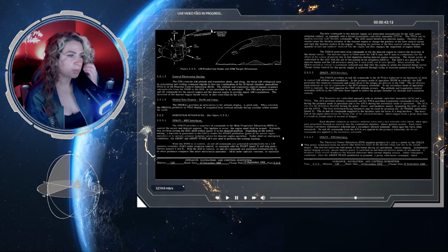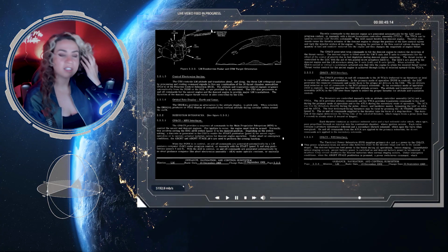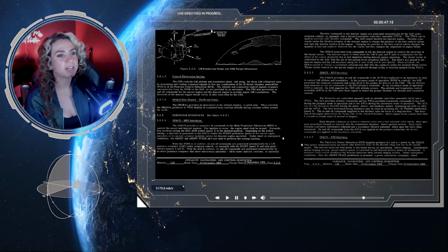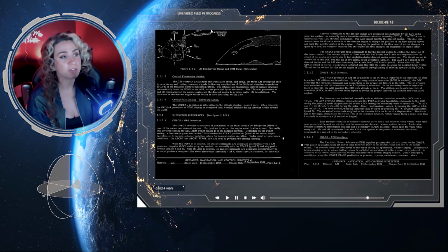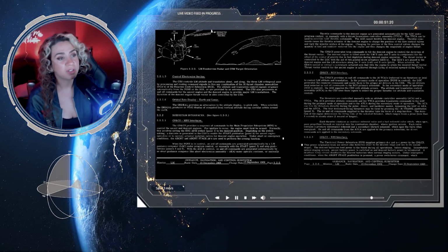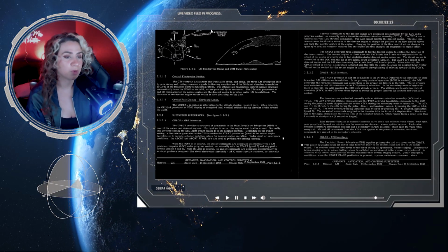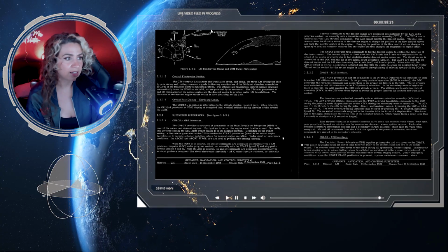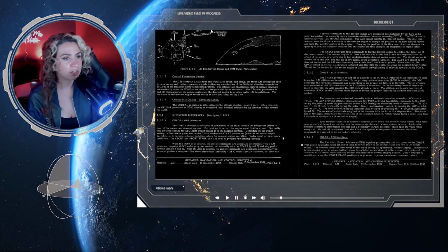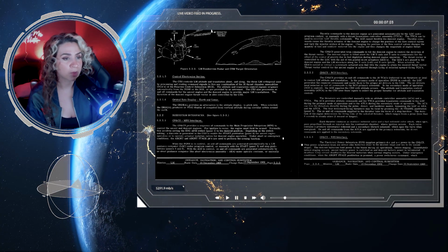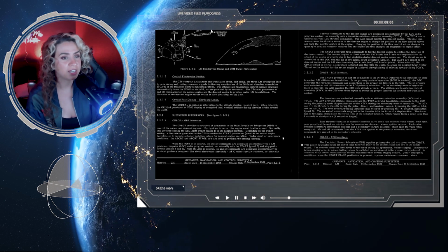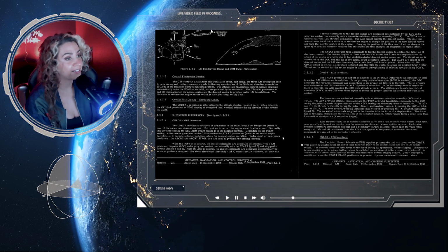The ACA provides attitude commands, and the TTCA provides translation commands to the LGC during the primary mode of operation and to the ATCA during the secondary mode of operation. The ACA can fire the thrusters directly during the pulse, direct, and hard over modes, bypassing the LGC and AEA in the ATCA.